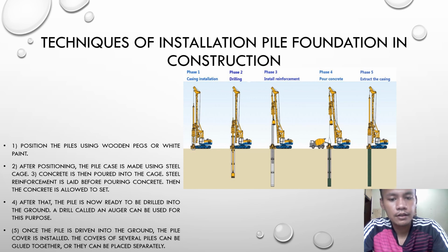If installation is to be carried out using the pile hammer, then the following factors should be taken into consideration, namely size and weight of the pile, driving resistance which has to be overcome to achieve the design penetration, available space and headroom on the site, availability of crane, and noise restriction which may be enforced in the locality.